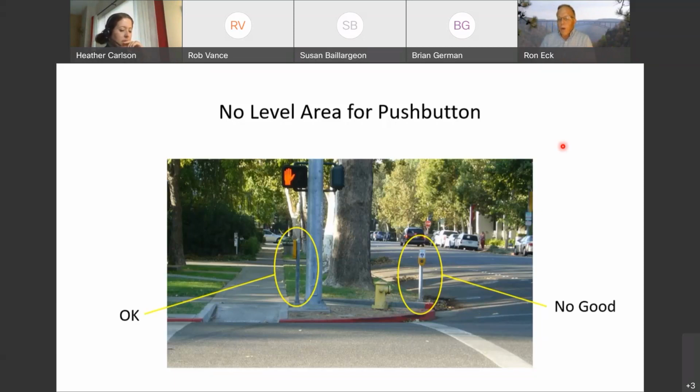And there the cross slope we measured was 13%. That's not an easy fix. They're going to have to think about what to do to get that down to 5%. Sounds good. Thank you. You're welcome. Good question.